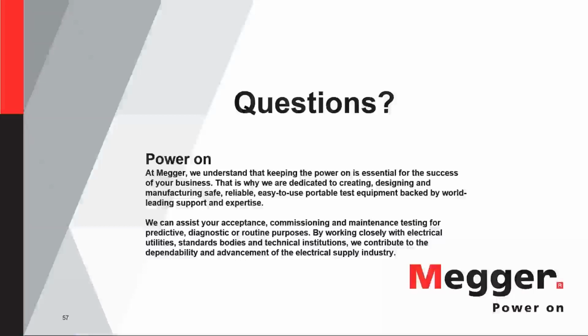All right, thank you. Okay, the last question we have for today: what is your opinion about using the sample port on the transformer oil valve? Well, that small port or little adapter to sample oil is mainly for syringes. The amount of oil required for the breakdown test is probably too much for it, and you will take more time than you want to spend there.